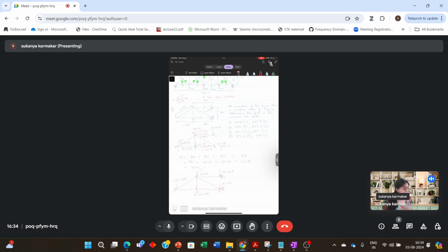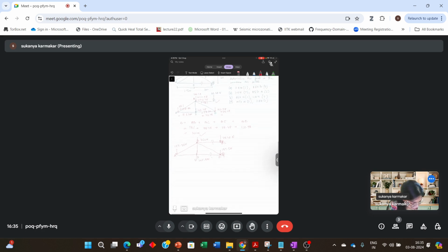Now, under this force, you can simply calculate the force in the member BC and this is straightforward. Either you can use method of joint or you can use method of section. See, quickly I'll, for a change, let's use method of joint. So let's pick up joint A. Let's do summation of force in the vertical direction to be 0.